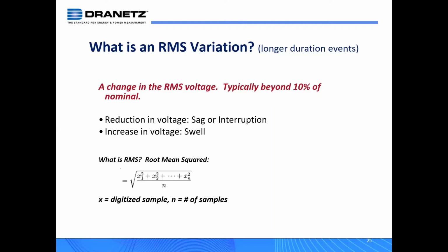So again, we are talking about the RMS. You take all the samples from one AC waveform, whether it be 60 hertz or 50 hertz, and you compute the RMS from that. So the example that I give here in the United States, it's 120 volts RMS when I plug into the wall. In Europe and other parts of the world, it's 230 volts RMS. It's not the peak of that that's used as a reference.